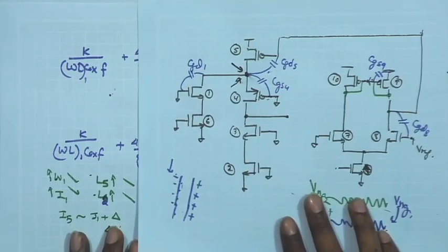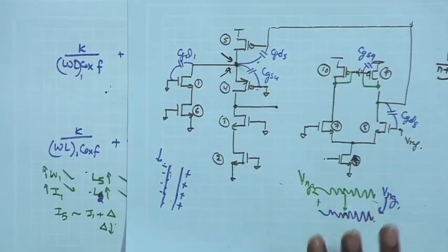So, as the next step, now since we have done this analysis for noise, frequency response, swing, etc., we will take a couple of examples where the design steps will be shown algorithmically. Given design specs at the higher level, how do you come back to the transistor-level design, and how do you approach the sizing of these different transistors step by step in a logical fashion, considering all these constraints and design requirements in terms of specifications? So, while addressing these specifications one by one, starting from say bandwidth, starting from the gain bandwidth product,